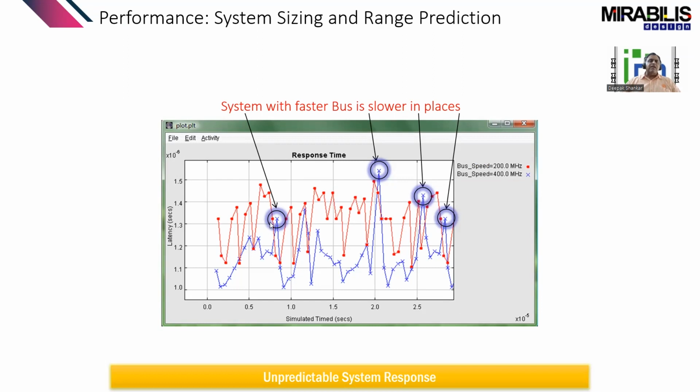If you look at this design, you will see that the 400 megahertz actually has peak values that are much higher than the 200 megahertz. Yes, of course, the 400 megahertz is in a lower power range versus the 200 megahertz, but you can see these peaks are there. So in this particular design, going from 200 to 400 megahertz is not really an advantage.